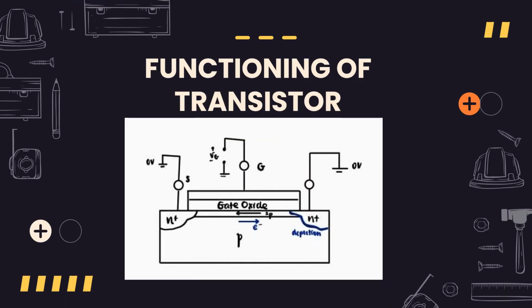Okay, so now here's a more detailed view of how a transistor is. We've got here our wafer, which was doped with a p-type. We have here the source and the drain. Here I forgot to write the D standing for drain. And here is the gate. The gate, as we had previously said, is protected by the silicon oxide, which is here, and the upper part would be the photoresist.